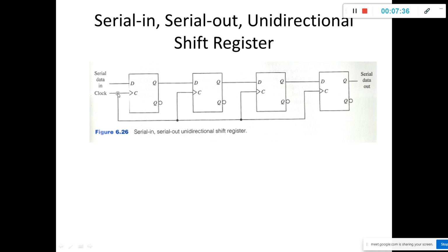So, upon the occurrence of the positive edge of the clock signal, the content of each flip-flop is shifted one position to the right. I repeat, upon the occurrence of the positive edge of the clock, the content of the flip-flop is shifted one position to the right.